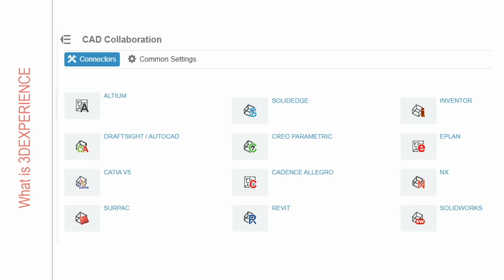So when you think about it, anybody that's had 3D Experience Platform administrative access, the platform management tools, you can go into the CAD connectors and you basically see this entire list. This is how we set it up to make attributes and properties and variables come in directly from the CAD files that are all variable, and then get put into things like the title and the description information on the platform.